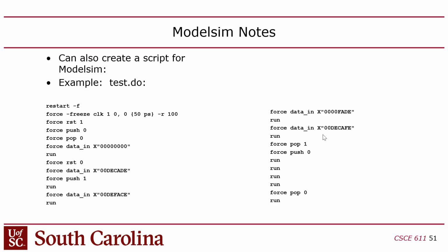So the idea is that you write this script and then you can validate that it's working by looking at the waveform, which is kind of a bad way to do it. It would be better if we had a way to automate this process, to check the outputs. But I don't actually know how to do that in Tcl, because normally the way you do that is through a test bench. You do that in Verilog, and I'll show you how to do that, because that's a requirement in Lab 2. So this is not a test bench. This is just like quick and dirty testing, basically, right? Where you can verify that things are working through the waveform. But if you want to have a self-checking mechanism where you write code that checks, I think you can do that in Tcl, but I've never done that because people use test benches for that. Okay.